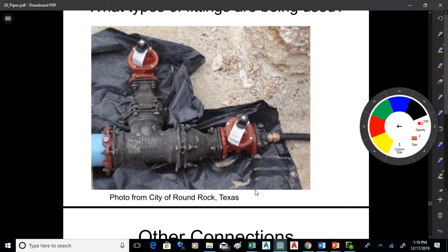Here's a connection that seems to have quite a few things going on with it. There's a flange connection. See how they're bolting. See, that's integrated into the fitting and the T there. That's a reducer actually. And then here's another flange. This one's a mechanical joint right here. You can see how that is a slidable fitting right there that you can slide up and compress the gasket with. This also has these kind of set screws where they're putting screws in that bite into the pipe and make for a stronger fitting.